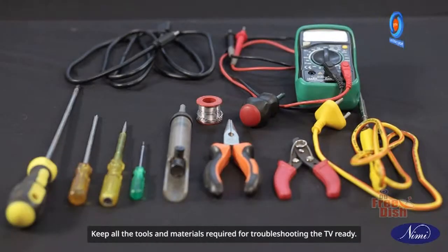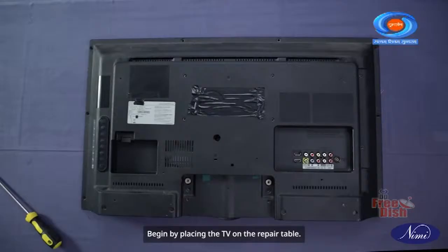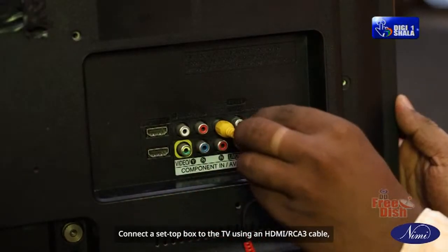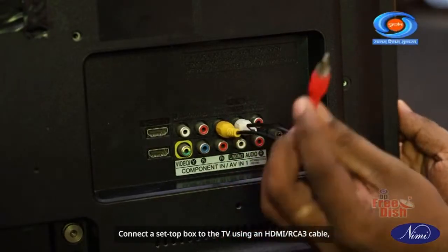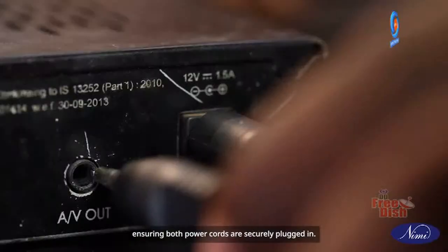Keep all the tools and materials required for troubleshooting the TV ready. Begin by placing the TV on the repair table. Connect a set-top box to the TV using an HDMI or 3RCA cable, ensuring both power cords are securely plugged in.